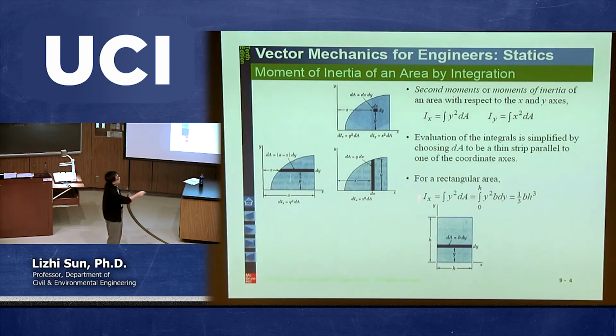Increasing b, obviously you're going to increase the moment of inertia. There's no doubt about it, but it's not very effective. If you want to increase this h, it's going to be very, very effective. So that's the first concept when you are using a rectangular beam. You would like to hold this beam this way instead of this way, because this way you have a smaller h.